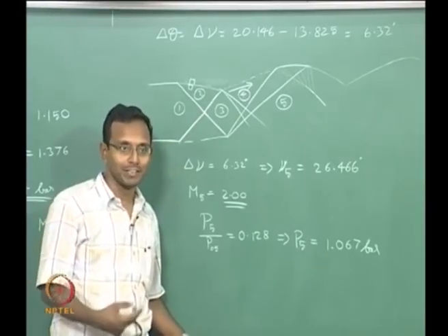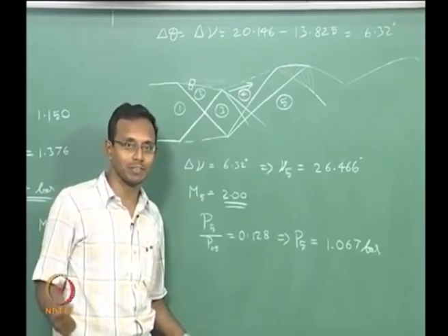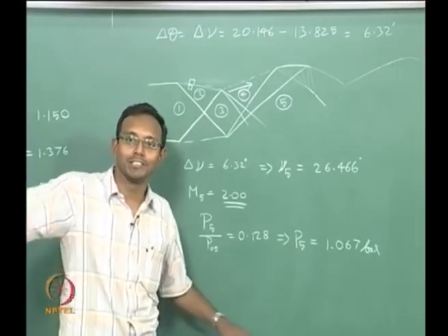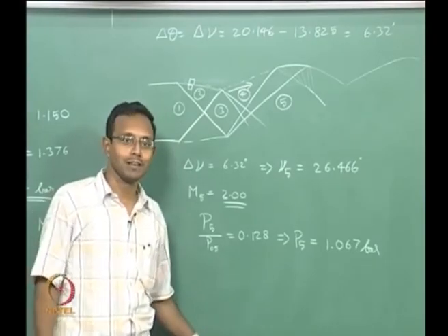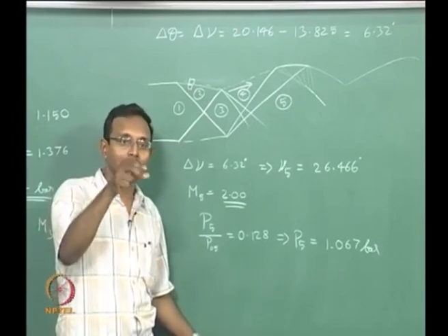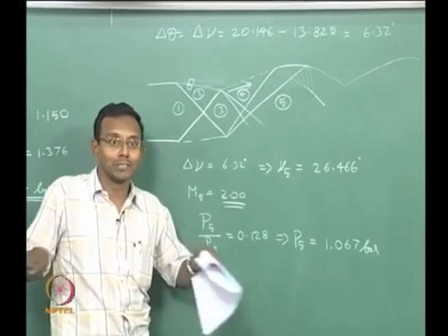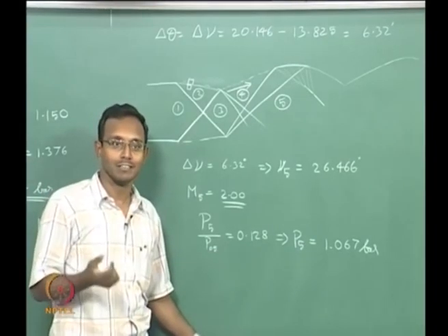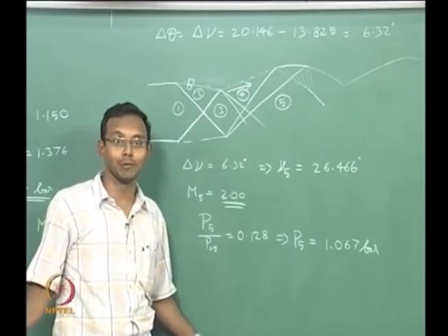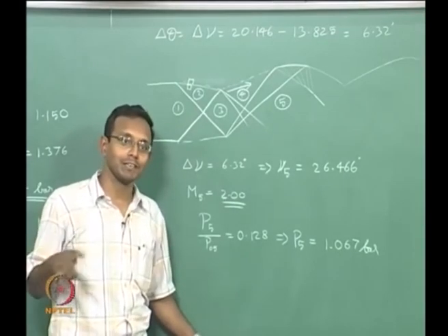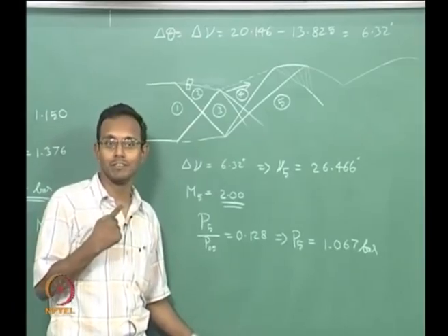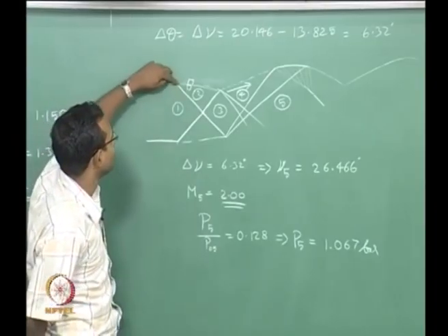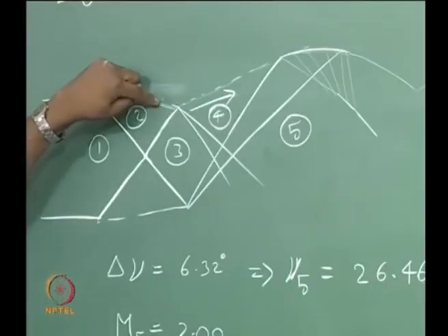In real life, if there is concentrated vorticity present somewhere, the viscosity factor will immediately come in and distribute this vorticity equally all over the place. It is like putting a drop of ink in water: immediately it diffuses out to all the regions, and finally you do not see any ink in the water. The whole water has the ink dispersed everywhere equally, until the diffusion finishes. Similarly, here viscosity diffuses the vorticity. The only place where you will see a serious amount of vorticity is this edge, the jet boundary alone.